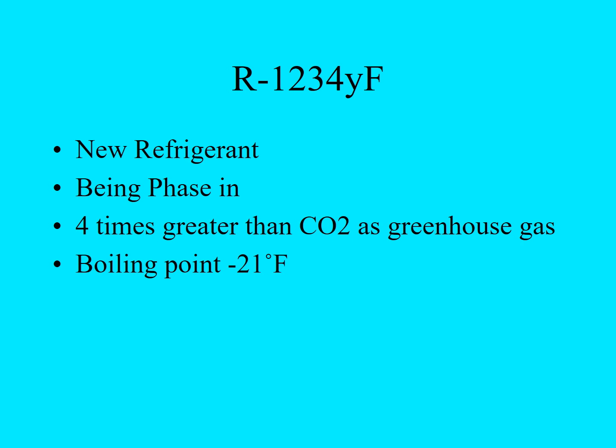So with the low greenhouse gas effect, and along with that, the other thing is it has a lower boiling point than R134A. So because of that, it would have a little better performance than 134A does as a refrigerant.